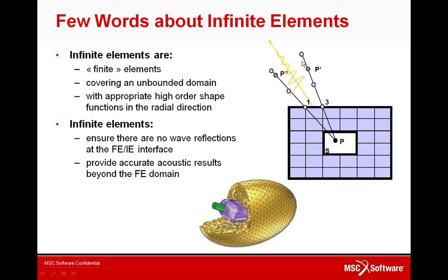The purpose of these higher order shape functions is to first act as a non-reflective boundary condition, meaning that an acoustic wave that goes in that direction cannot come back in the other direction. And then it's also used to compute the pressure fields far away from the source.